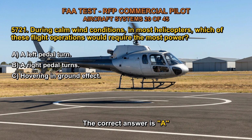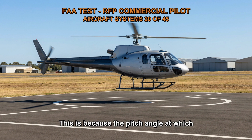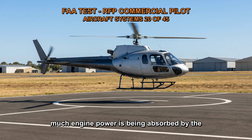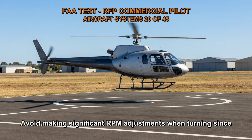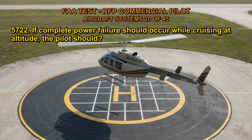The correct answer is A. If no throttle is provided, the RPM will fall during a hovering left turn. If the throttle is not slightly lowered, the helicopter hovering to the right will see its RPM rise. This is because the pitch angle at which the tail rotor blades are rotating determines how much engine power is being absorbed by the tail rotor. Avoid making significant RPM adjustments when turning, since this may cause the nose to move erratically owing to torque variations.